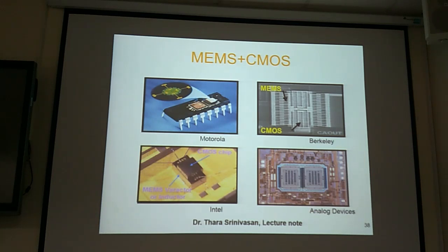So we need amplifiers. But we also need a filter because we have a lot of noise: from our power source, from temperature, from vibration, or from the circuit. So we need a lot of electronic devices to help the sensor get the signal out.